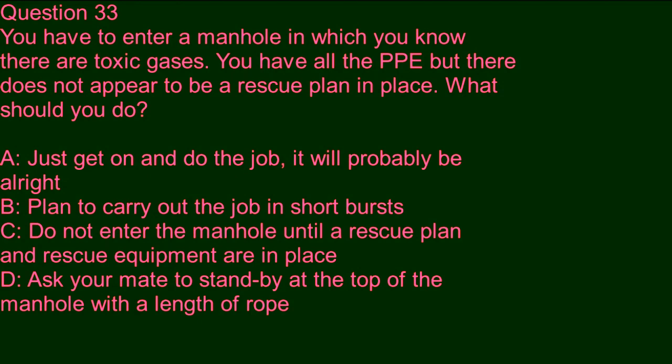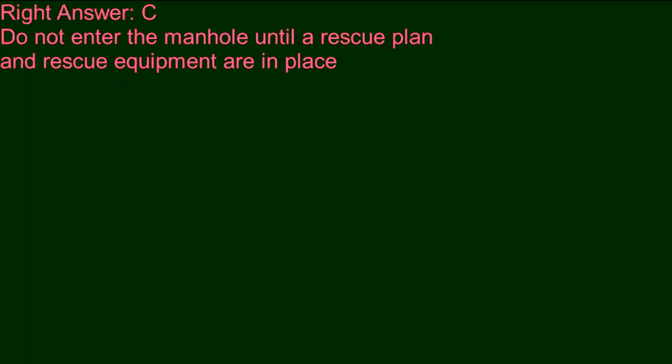B. Plan to carry out the job in short bursts. C. Do not enter the manhole until a rescue plan and rescue equipment are in place. D. Ask your mate to stand by at the top of the manhole with a length of rope. Right answer, C. Do not enter the manhole until a rescue plan and rescue equipment are in place.